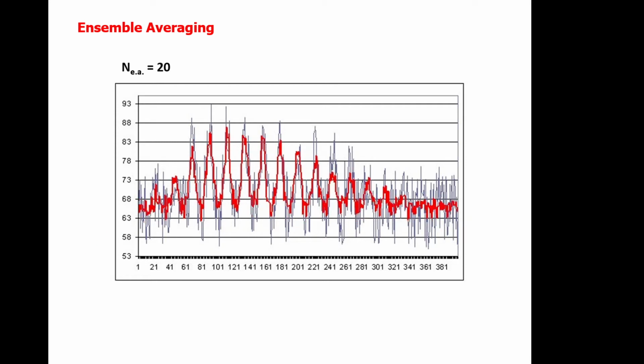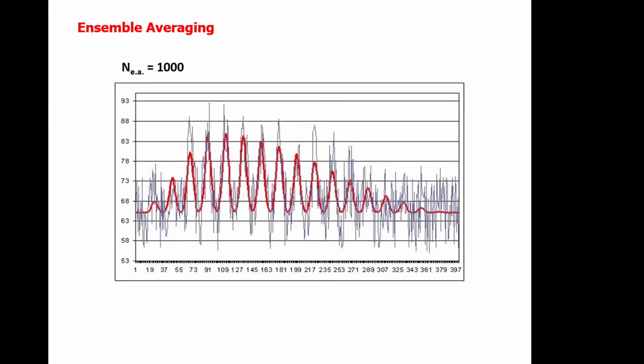There's still noise there, but the average of the noise has been reduced. If you take 20, it starts to improve even more. 50, very nice, starting to see the signal in this noise. 100, it's starting to get there, and if you keep going, it just improves matters. And if you could take 1,000 samples, then you're starting to see a very smooth plot in the data coming through, and we got rid of the noise.